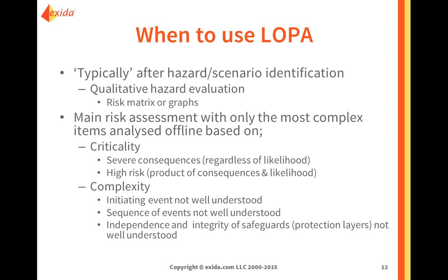So that's reasons to do LOPA. At some companies, they tend to do LOPA all the time. You need to be a little bit careful with that. It's absolutely a good approach, but it can be very time-consuming. Now, you could argue, if a detailed analysis suggests that you need a SIL 1 instead of a SIL 2, you save a valve, so to say, and that may pay for the extra effort that you go through.